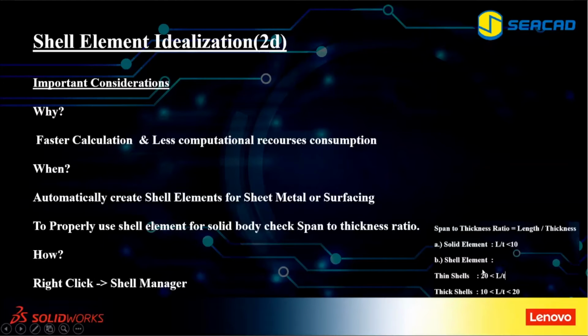But if the length over the thickness is more than 10, then it will be better to use the shell element, because experiments have proved that the results are quite similar whether you use the shell element or the solid element to run the simulation. So remember this one. As I mentioned before, the questions in the quiz are from my slides.